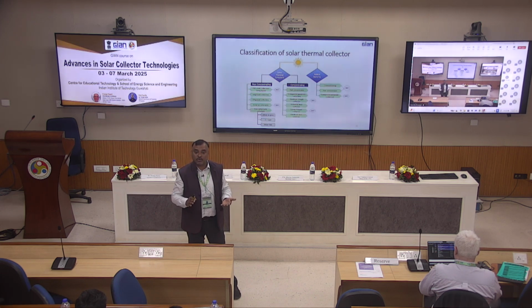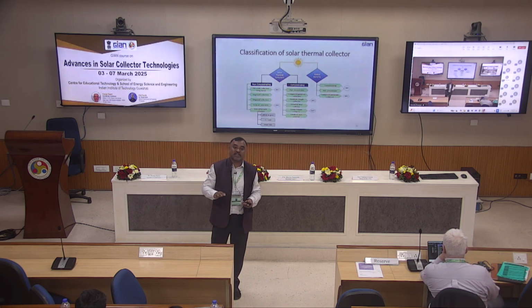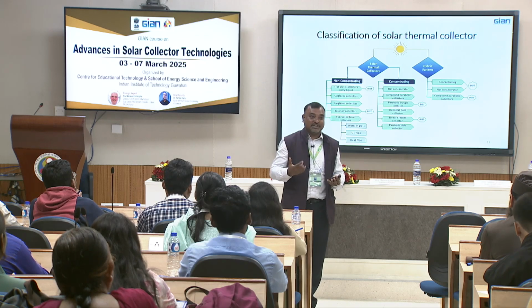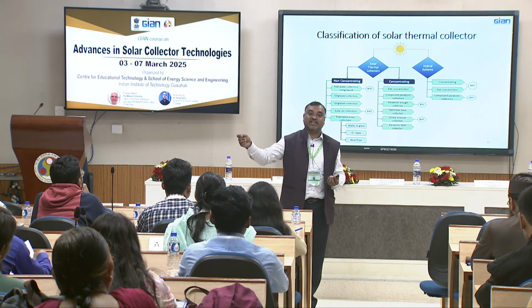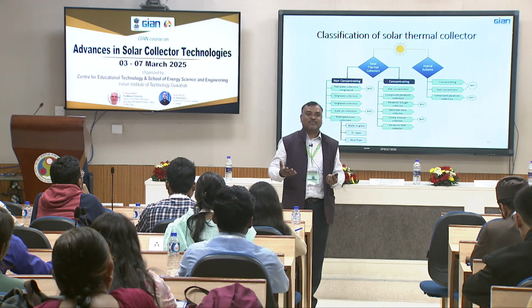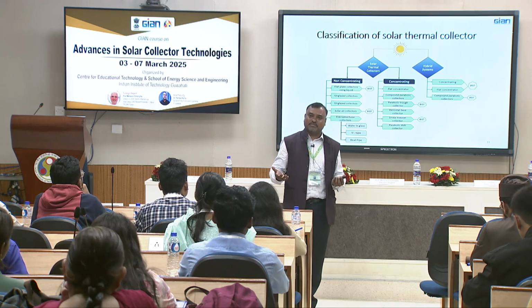Okay. If we work with a flat plate collector, suppose you have a flat plate collector, but your demand is to generate electricity, it is also possible, because you have organic fluids which boil at low temperature, and you can generate some vapor, and that is okay for generating some kind of power. But the efficiency of that kind of collector is very low. It is about 5 to 7%.